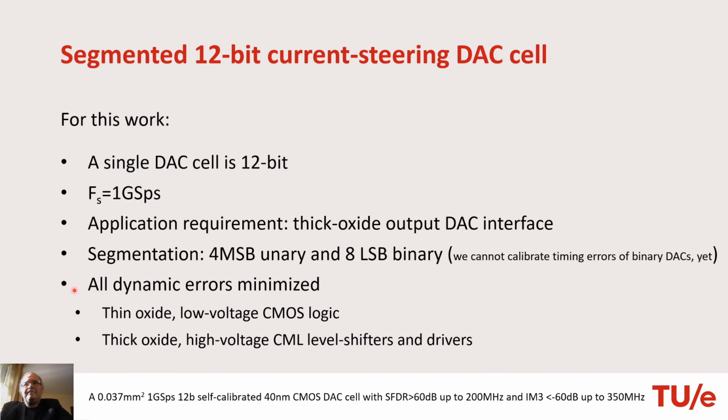And to minimize all the dynamic errors, so that we keep good performance, good linearity at high frequency, most of the switching digital part is implemented in low voltage CMOS logic with thin oxide transistors and very small area, including the synchronization.